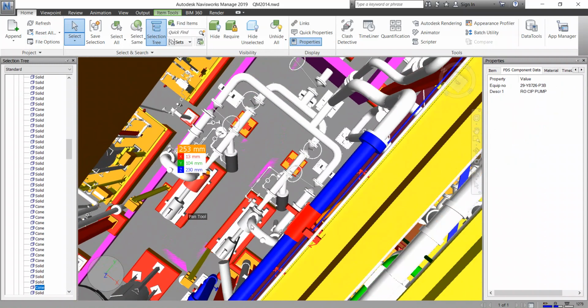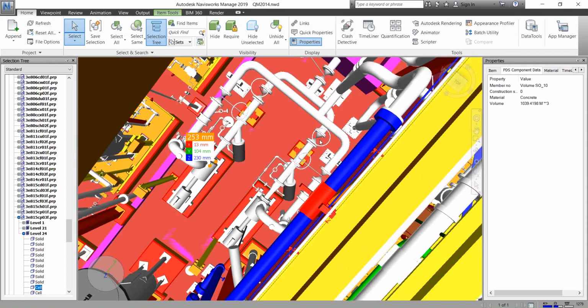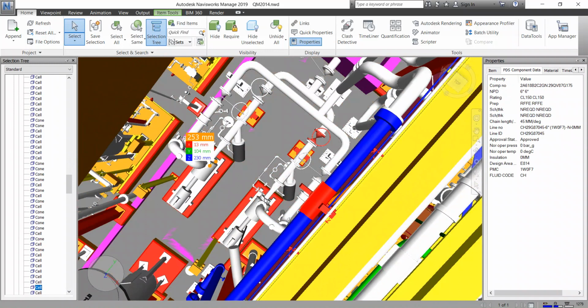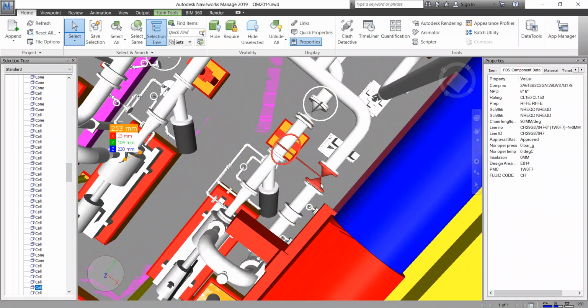If this one is in standby condition, then from this valve to this flange, and for the discharge line from here to this one, you have to make the temperature ambient, since there is no fluid flow.